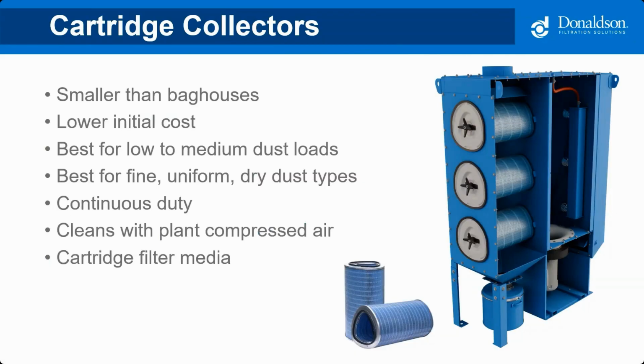They're designed to be continuous duty, so you don't have to shut them down when it's time to pulse or clean the filters. They clean with plant compressed air, and they use smaller, easy to handle cartridges, which change out much quicker than a traditional bag and cage.